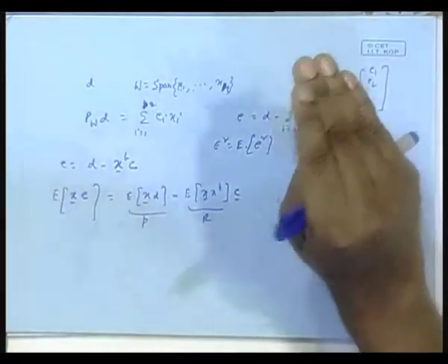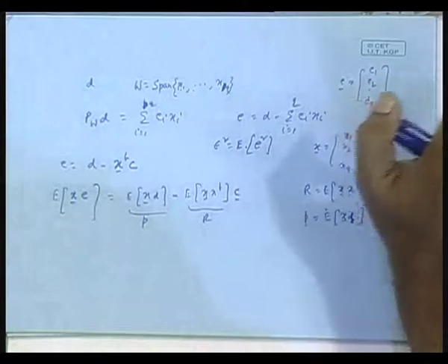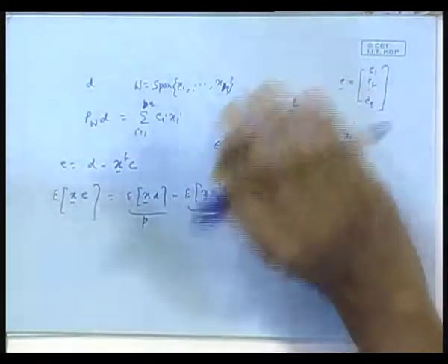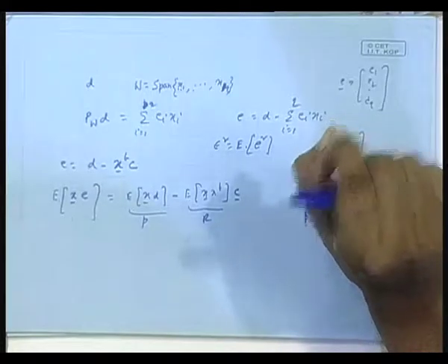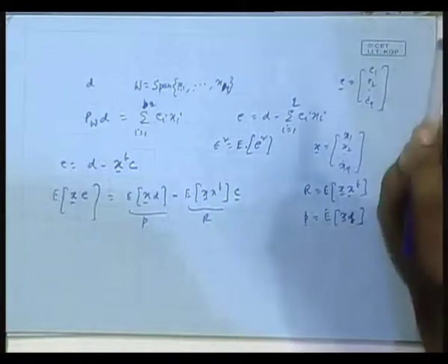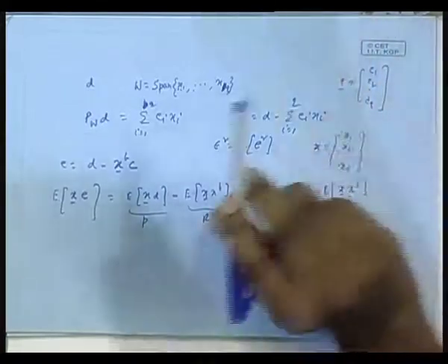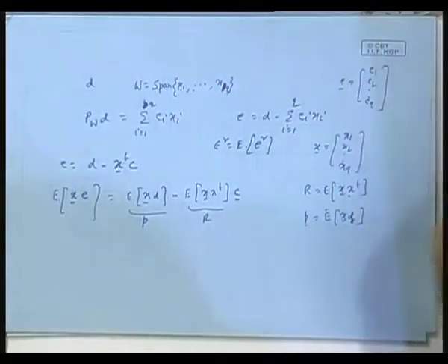So, I am introducing approximations there, and immediately I am paying a price. What price? I can have convergence subject to proper choice of mu, but it is not exact convergence, it is only convergence in mean. So, it is not that filter weights will converge really on the optimal one, it will be dancing around the optimal one, the mean of that being the steady state, as n tends to infinity, but of course, we really do not have to go for n equal to infinity.